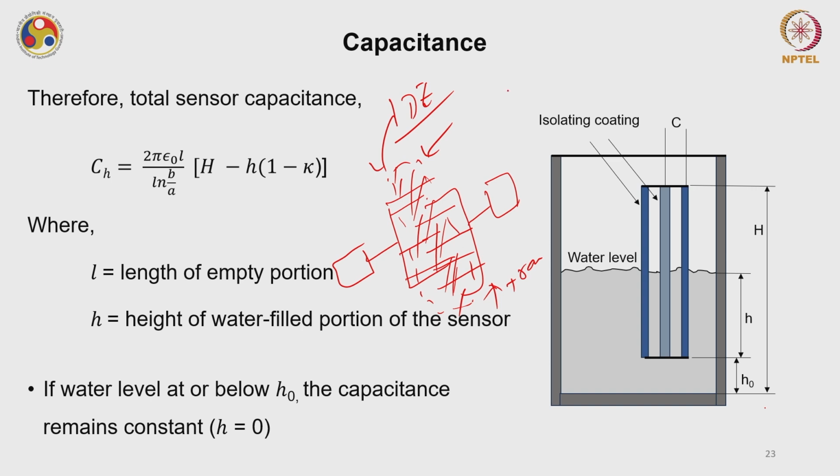Now when some gas molecules interact with this sensing film, what will happen? It can either physisorb or chemisorb with the sensing film. Because of that, there will be a change in the dielectric properties of the material. Either it will increase or decrease. Say the initial capacitance was C1 and now it has increased to C2.